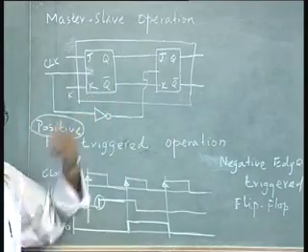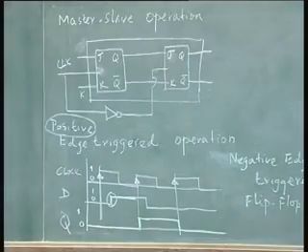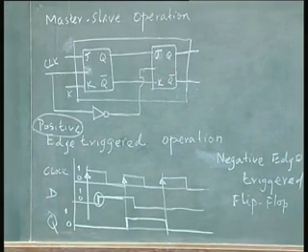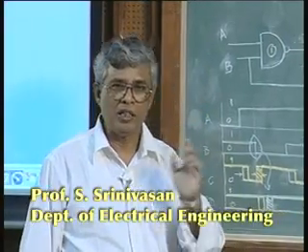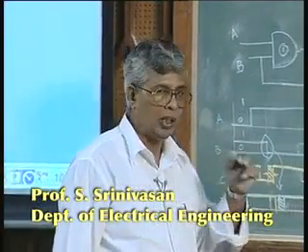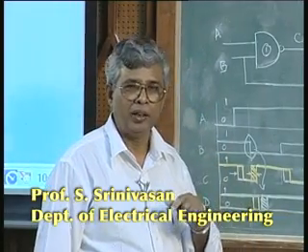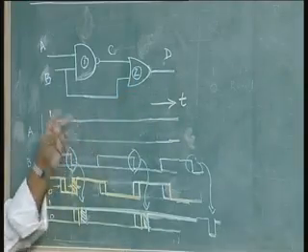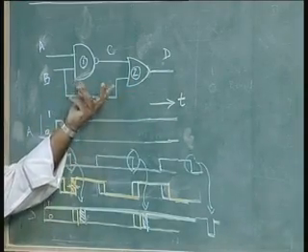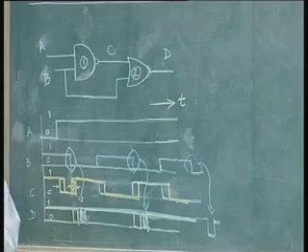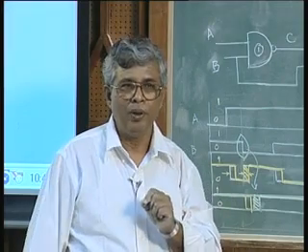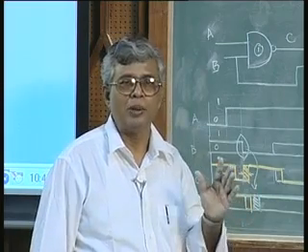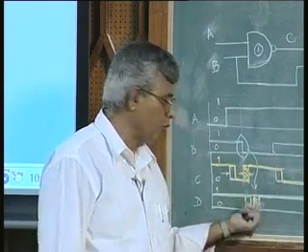Now, that is not all quite true, I need to add to the input of each of the edge triggered flip flops, whether it is a JK flip flop, SR flip flop or a D flip flop, whatever is the edge triggered flip flop I am constructing, to each of the inputs of a flip flop other than the clock input, I need to add a little edge triggering circuitry. This circuitry shapes the input into narrow pulses which will only be applied to the flip flop, and only under that condition the output will change, the rest of the time the output will not change because the input is removed after that narrow pulse period.